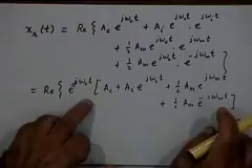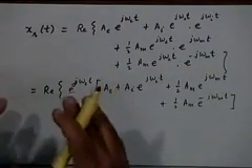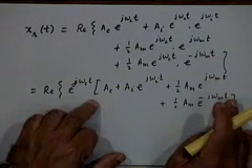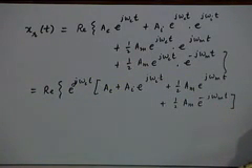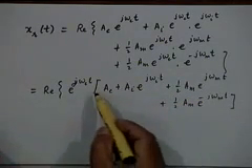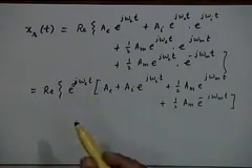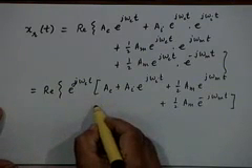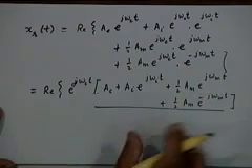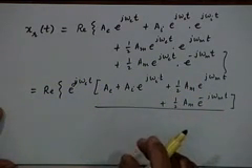So every term is rotating at that frequency, so you can now think as if, as far as these components are concerned, you are working in a stationary framework. If everything is rotating, then with respect to this it is stationary. So we will only look at these components and draw the phasor diagram corresponding to these.